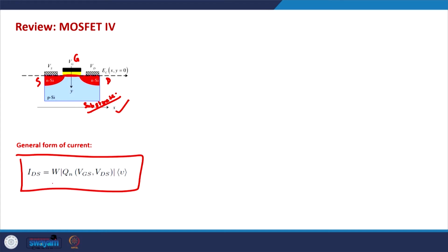IDS, the current from drain to source, is essentially dependent on two factors. One is the charge in the channel, Qn(VGS, VDS). This Qn charge depends both on VGS and VDS, and it depends on the velocity at which this charge is moved across the channel, which is a quite intuitive definition of the current. In addition, it depends on the geometry, on the width of the transistor.